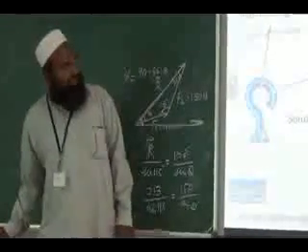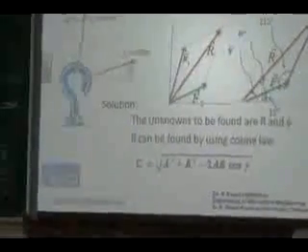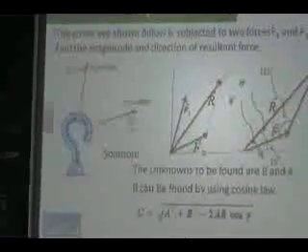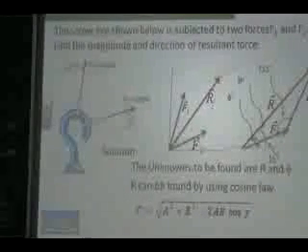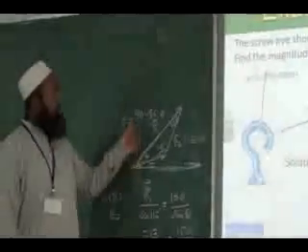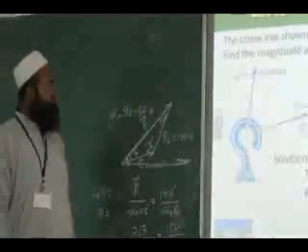This is theta, the included angle between F and R, whereas we need to find phi, which is the angle made by the resultant with our x-axis. That is what we have to give finally. That can be obtained by considering 90 as the total angle and subtracting.